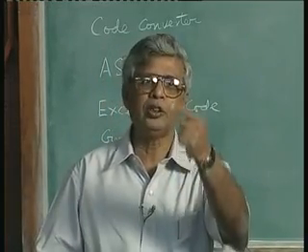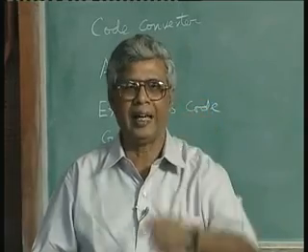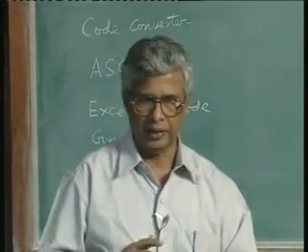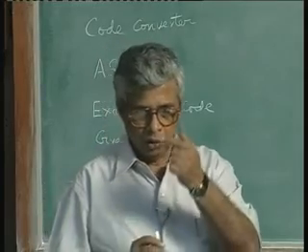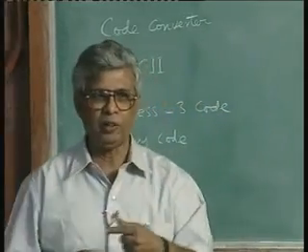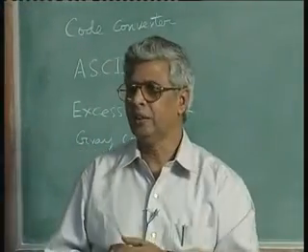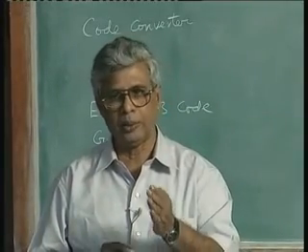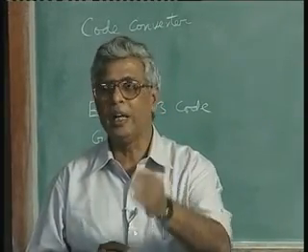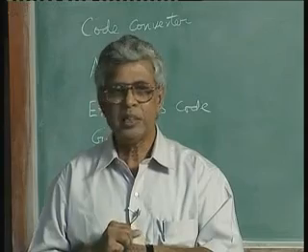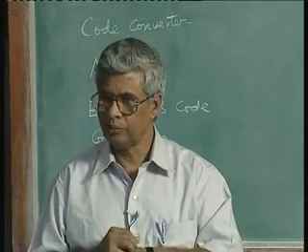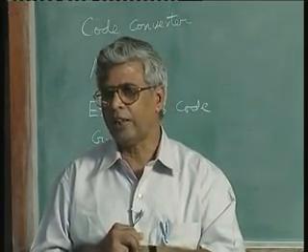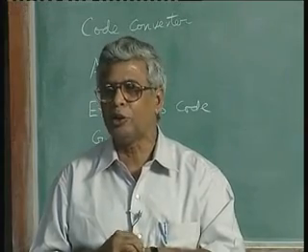Suppose I need to switch only one switch at a time, whatever be the magnitude of the number, from one number to the next number. That reduces some activity. Switching activity represents speed of operation. Switching activity represents power consumption. These are the things which you have to take from me now, but you can think of intuitively.